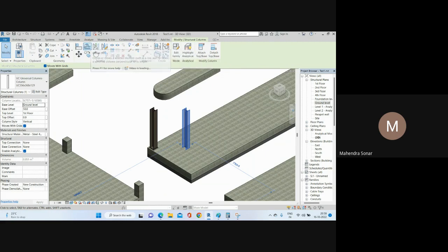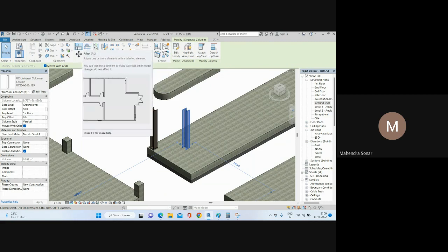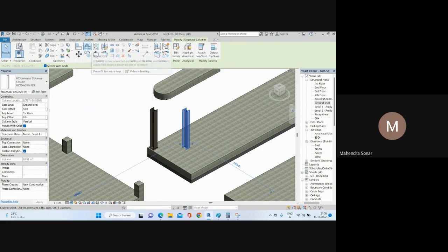So most of these are sufficient for now. So move, copy, rotate. Then you have the option offset also. Then here align. Okay, so AL. If you type AL, you can give the align command, and OF for offset. So just write down on paper these 5 to 6 commands. For now this is sufficient for whatever the basic Revit work here. Okay.